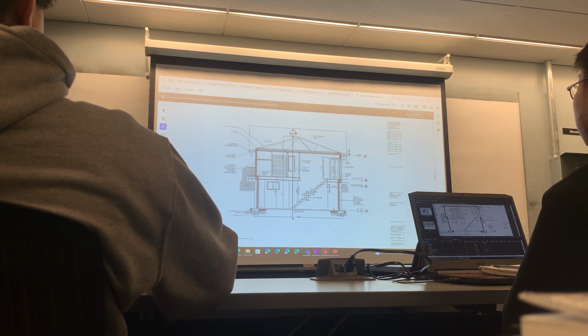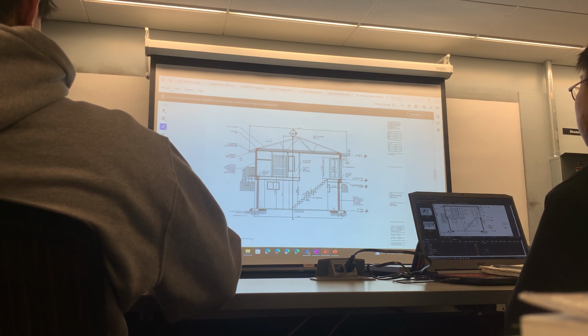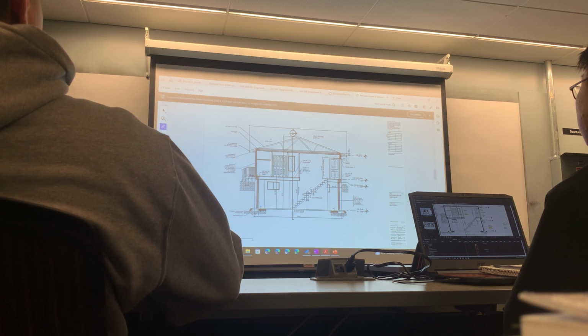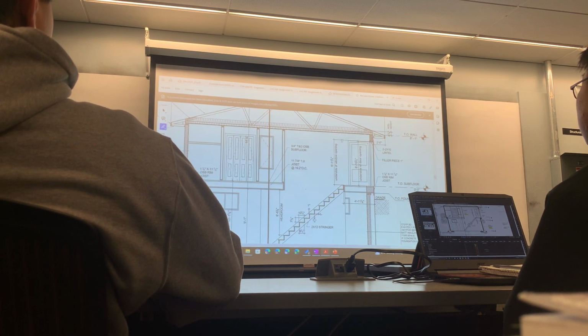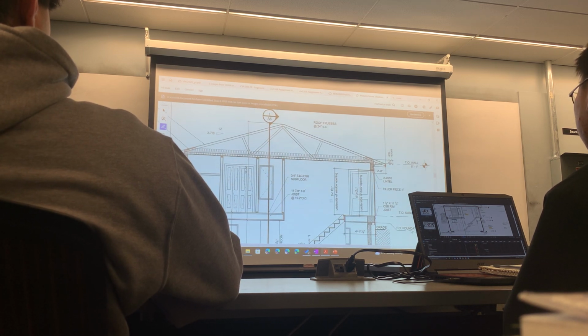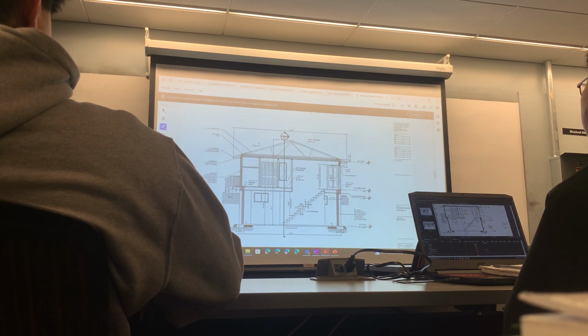You've got your 2-foot overhang, so that's going to help you get your gravity loads from the roof. You're going to get the wind loads from the calculation of P and PI. And from these walls, we're going to get heights. This doesn't give really good heights. This is 14'5" to the top of the roof. These dimensions aren't helpful, but if you go to the other section,